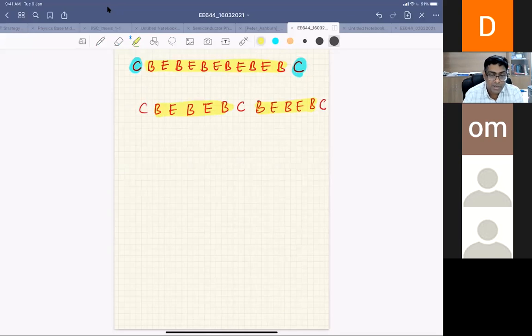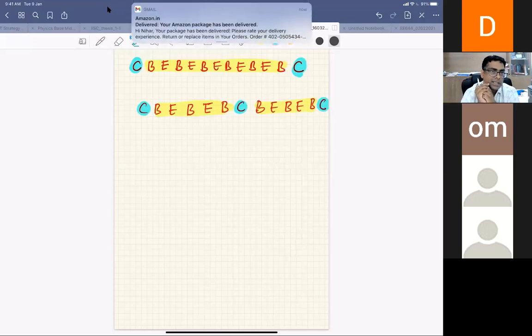But I have inserted the collector in between, so that collector resistance, because the collector also has a finite resistance, is not a factor. It will be a factor when you go to frequency, meaning fT and fmax.